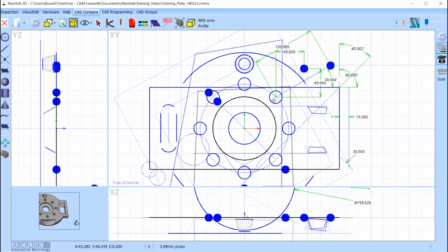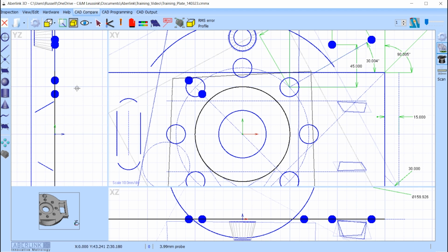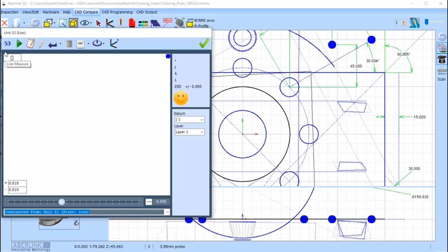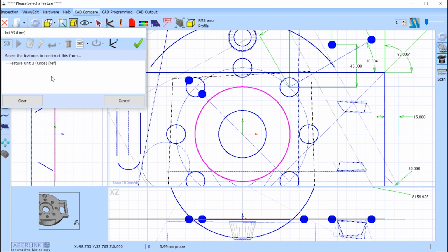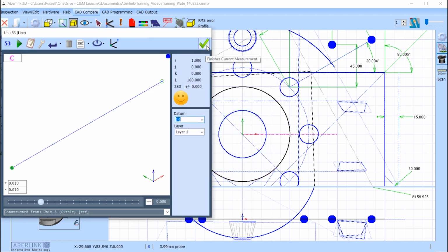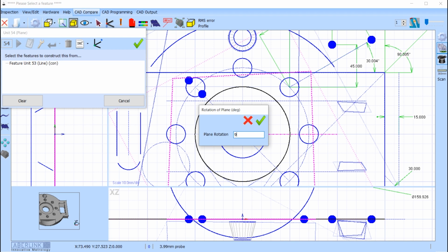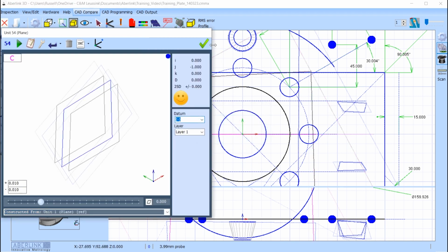Finally, plane construction. As you've seen before, I did a perpendicular plane through that line in the main plane. Very, very straightforward. If I wanted to put a plane through the centre of my datum, the C, what I would do is put a line in first from the circle, hit the circle again. Let's go about 100 millimetres. That's our X. What I can do is now do a plane from that line, from our datum plane, at whatever angle you require, but let's call it 90 degrees.